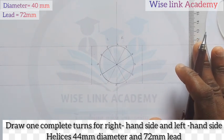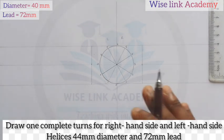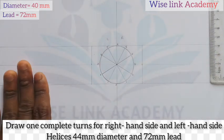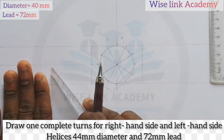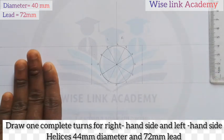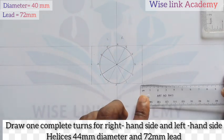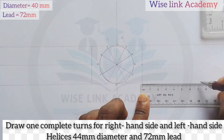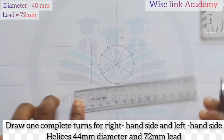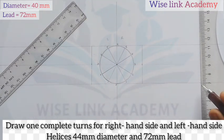Now my next task is to measure out 72 to the left and the right. Naturally it is left, this is right, but in terms of helix it becomes right, left. So I want to draw my left hand first. I'll measure out 72 from this point to this point, and place my T-square to draw a vertical line this way.